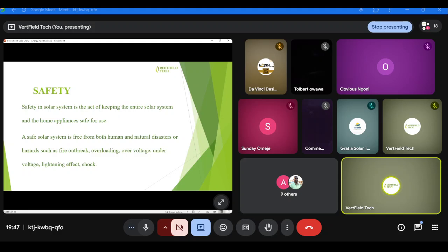That is where we took our time to explain certain parameters like voltage drops, and while sizing the cables, we use tools like online voltage drop calculators. Yes, that is what we use. We talk about the sizing using your ISC, your VMP, and the rest of the solar system parameters. A whole lot we do in the advanced class.